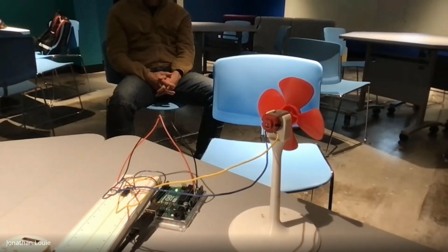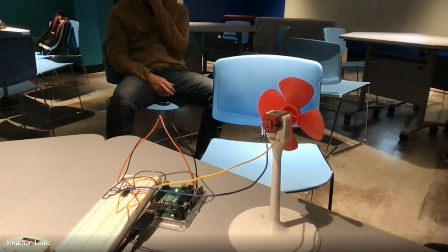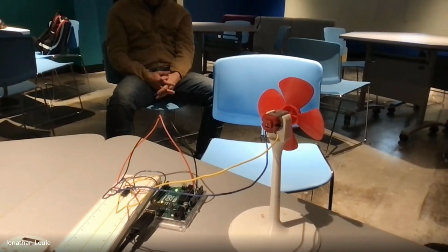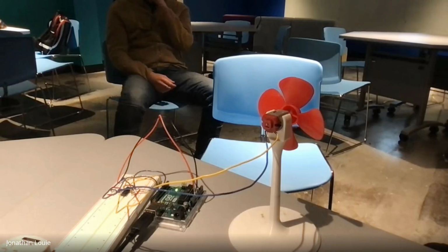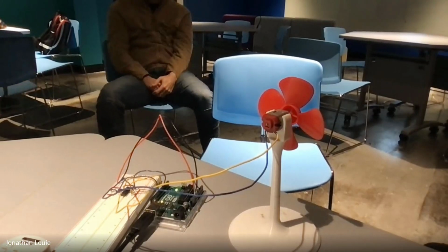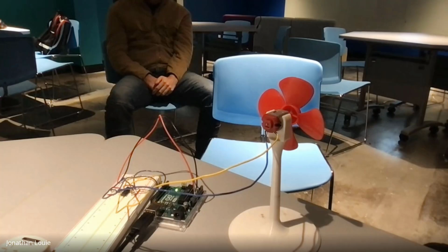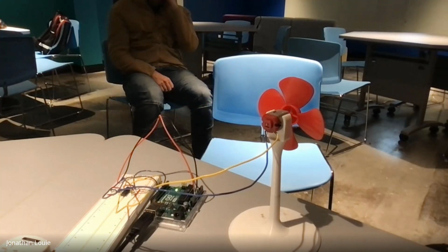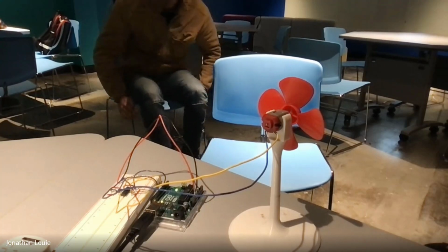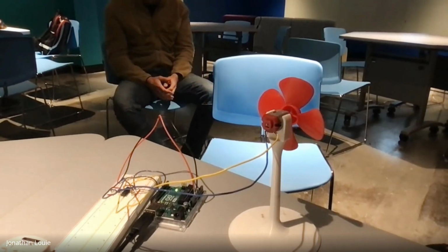The EM waves coming from the sudden change in current with the actual bolt of lightning are enough to couple onto those lines and cause fuses and stuff to blow, because any line is basically an inductor. The inductance is very small, but when your frequency is high enough, everything is an inductor, everything's a capacitor.